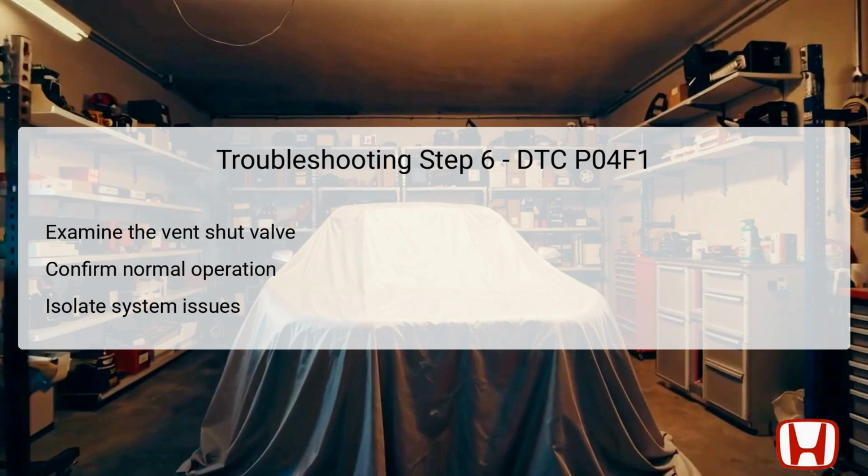If the previous evaluations have indicated normal conditions in other components, it's likely that the vent shut valve is at fault and will need to be replaced to resolve the P04F1 DTC.